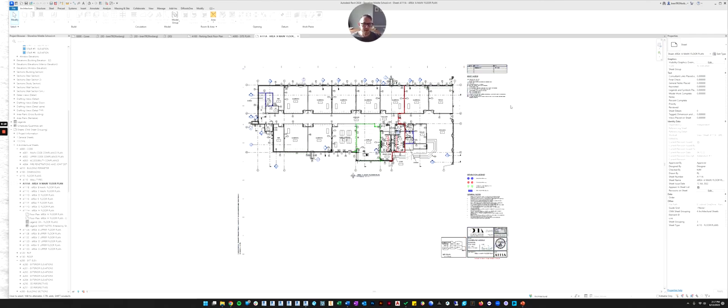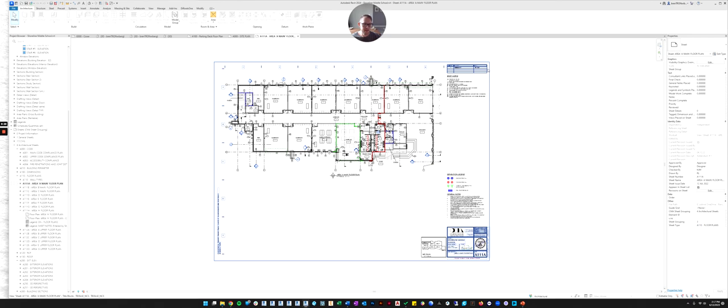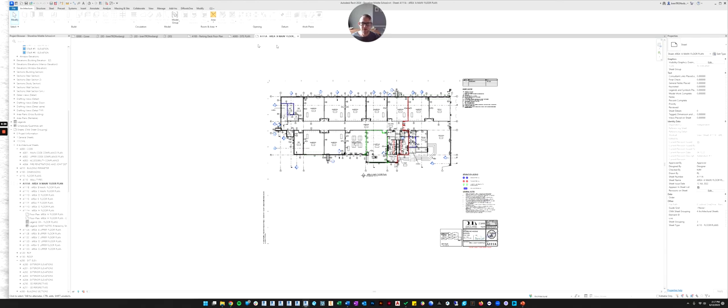So their title block is even more simple than mine, kind of. They don't even put a border around their title block, which I suggest putting, because it helps you know where to place the views. If your title block doesn't have a border, then you sometimes can't tell what is out in space and what's going to end up on the sheet.